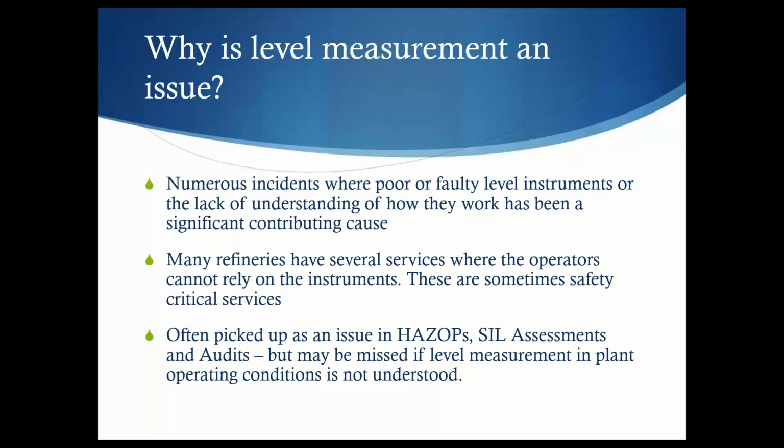Yep, there's various services, not just on refineries, but elsewhere, where they rely on the instruments to work and do the right thing. And sometimes they can be a safety critical task, like preventing a blow-by from a high to low pressure system to prevent overpressure downstream. Obviously for overflow, it would be to stop the hazardous fluids going into the atmosphere and causing a flammable or toxic environment. Or it could be that it spills into another system that's not designed for it. And the same in Texas City, it could be that it actually goes into a vent stack that eventually overflows the vent stack, if one system fails and then the next one isn't ready for it or can't react.